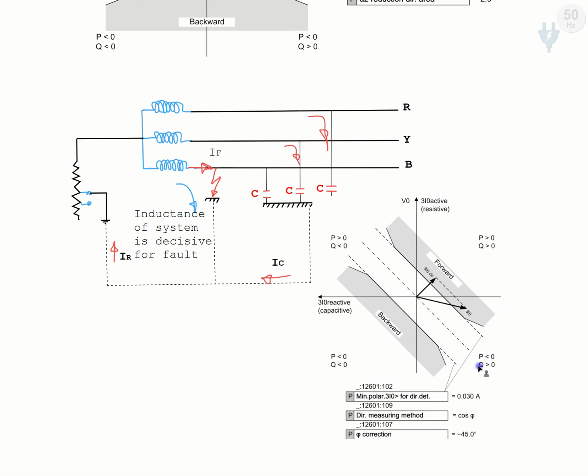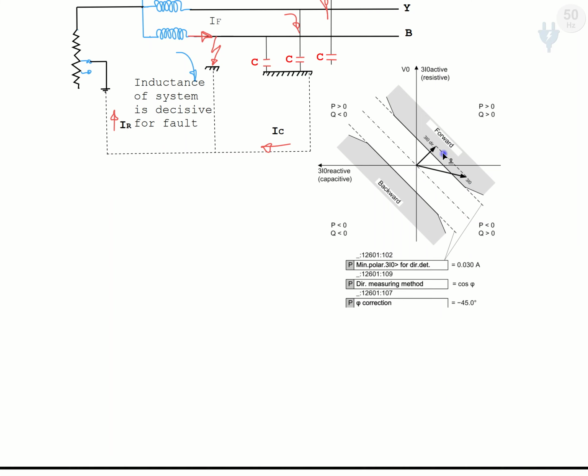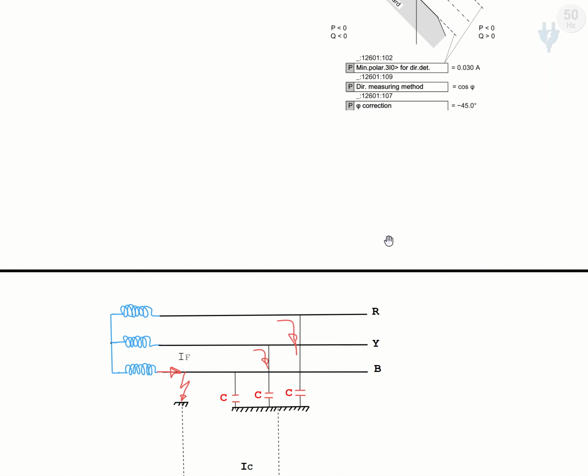We tilt the symmetrical axis because mostly the current which is in the system is more inductive, because the impedance of the system during the resonant conditions try to neutralize, and here the capacitive part of the current and resistive part of the current try to compensate each other, and the remaining important part of the current is the inductive part of the current.